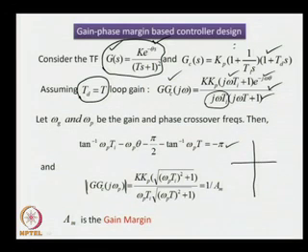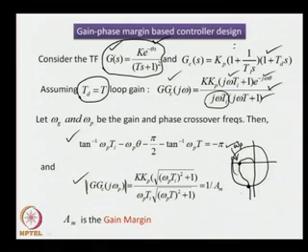Suppose we have the Nyquist diagram and this is our Nyquist plot. Then we have the phase crossover point here at the frequency omega p, which is nothing but the phase crossover frequency. So, this point gives us these two equations. Similarly, when the unity circle is considered, it gives us the gain crossover frequency omega g at this point, the gain crossover point, and thus that will also result in two equations.